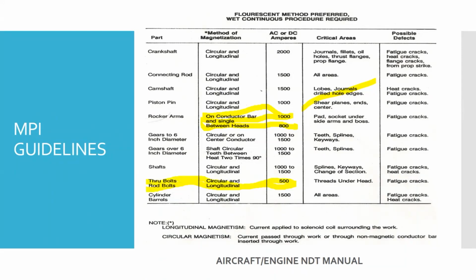So we have these charts. I don't have charts for every possible part you could test in there, but you can kind of get an idea of size, right? If you're going to put a part in that's similar in size to a crankshaft, you're going to need to turn that current way up. If you're doing a little part or something skinny, like a valve or a valve stem, right? You've got to back that current off quite a bit so you don't cause damage and overheat it. And that comes into play when you do your self-design projects. If you choose magnetic particle for part of your self-design, you can use this as a guideline for how much current to run on a given part.